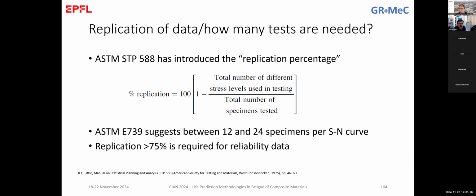And yes, I just have one comment, maybe a question here, that most probably the ASTM E739, while suggesting this formulation, assumes that the fatigue life data is log normal distributed, if I remember it correctly. Many times we see that the fatigue life scatter data is not following the log normal distribution, and then we find some issues with this particular formula, which is although a part of the standard anyway. It is a very old one, which is there.